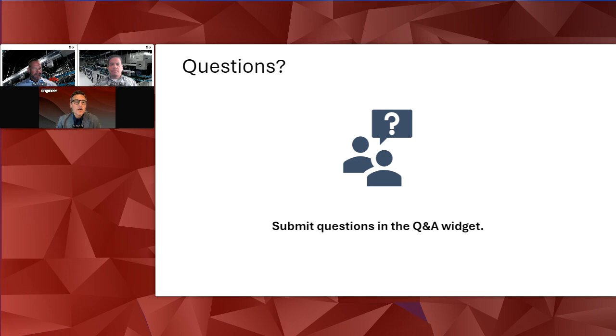Got it. Can IR thermography be used to evaluate phase load imbalances? Yeah, I can jump on that one. That's a great question. It can. Whenever you have the thermal image up, you're going to see if one phase is warmer or hotter than the other. A technician trained on a FLIR camera or a thermography camera will be trained to recognize that. Typically all three phases should be really close in temperature.